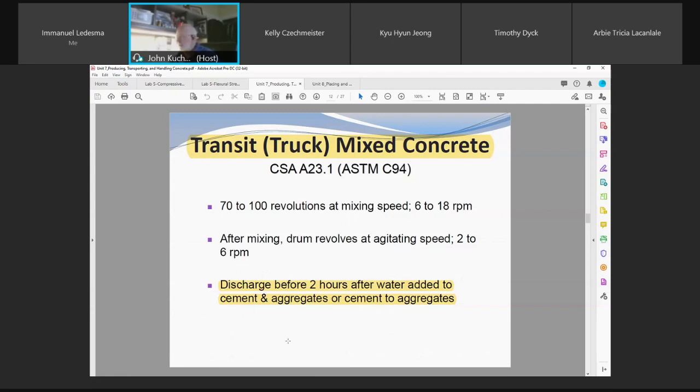That's why some of you may have been on a job site where you've looked at a ready-mix ticket. If you're inspecting placement of concrete for the City of Winnipeg road, you'll look at a delivery ticket and see a timestamp. Every delivery ticket has a timestamp. That time should tell you as an inspector, and tell the contractor, superintendent, whatever, that the water and cement came into play at 12:30 p.m. They started batching that load. From 12:30 to 2:30, it's got to be discharged in that time frame, maximum. Which isn't always right, because that 12:30 timestamp is not accurate.